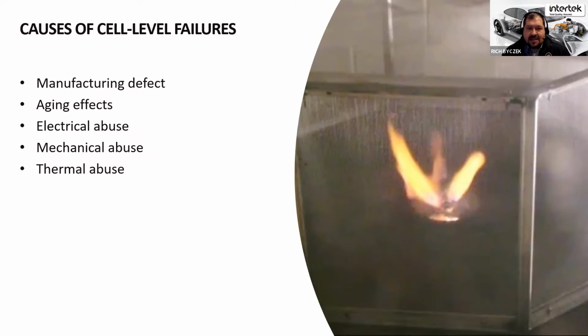I bring that up because when we talk about short circuiting, over discharge, and overcharge, it's where the battery could go beyond 100% state of charge or be driven below 0% state of charge. There's still energy content available. There are still reactions that can occur that aren't intended within the battery that can build up gas. So electrical abuse is one of those major concerns that can be somewhat addressed, at least through engineering controls.